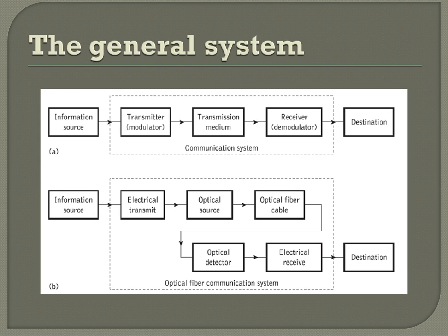The optical carrier may be modulated using an analog or digital information signal. With the digital information, the discrete changes in the light intensity are obtained. Although often simpler to implement, analog modulation with an optical fiber communication system is less efficient, requiring a far higher signal to noise ratio at the receiver than digital modulation.